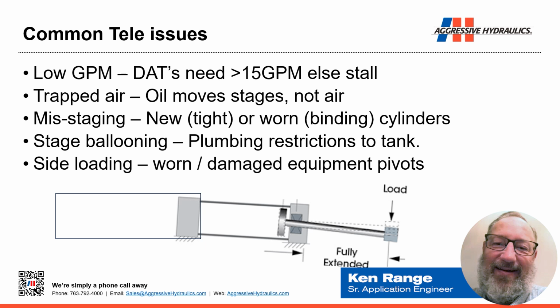Misstaging we talked about, and we've got to remember that these are wear components. Over the life of a cylinder, they break in, they wear. So therefore, misstaging of a new cylinder can be caused by manufacturing tolerances. In other words, one stage is very tight, one stage is very loose, and they can misstage then appropriately.